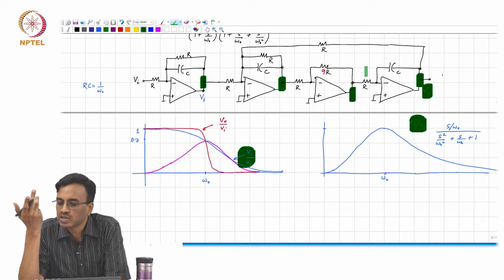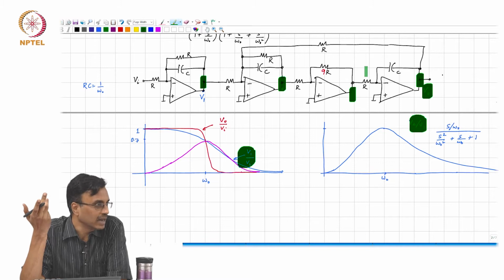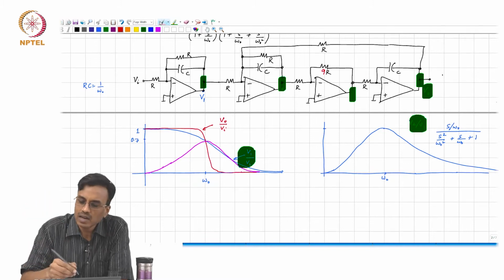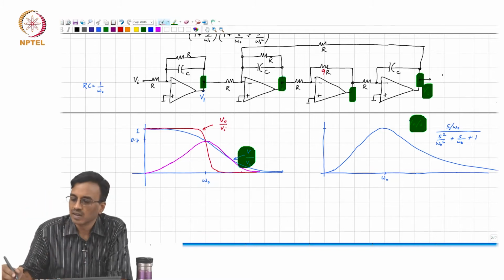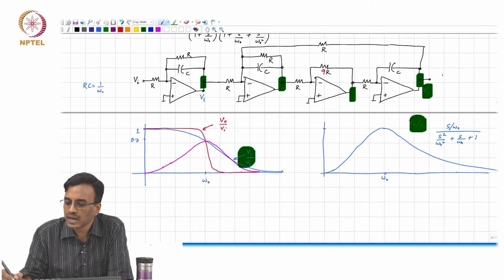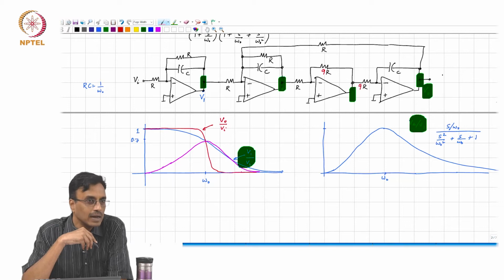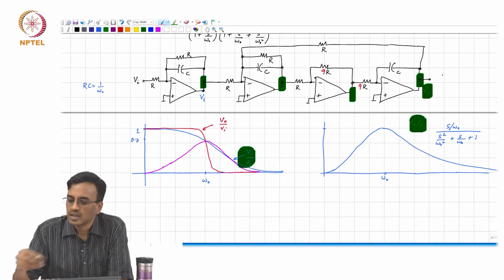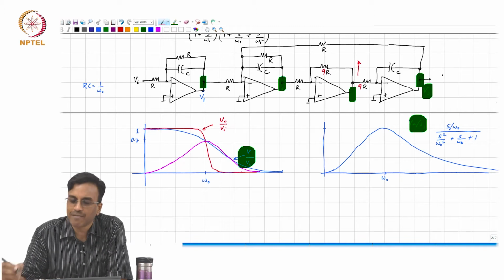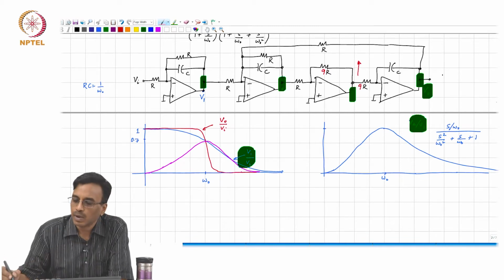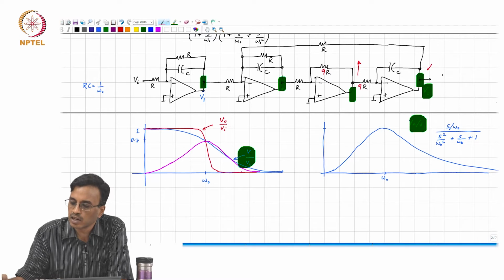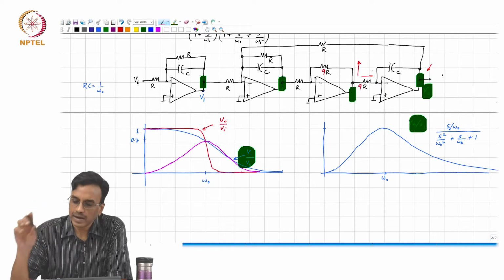Okay, one thing you could do is increase the capacitance by a factor of 9, right? Alternatively, there are many ways of doing this. An alternative way would be to simply increase this resistor also by a factor of 9, right? And what is the intuition behind that observation? So this voltage has gone up by a factor of 9, right? But if you want the transfer function here to remain the same, this current should be divided by 9, that's all, correct?